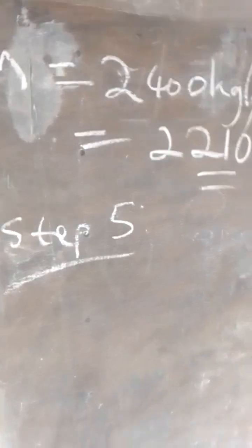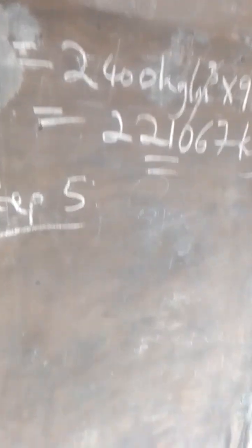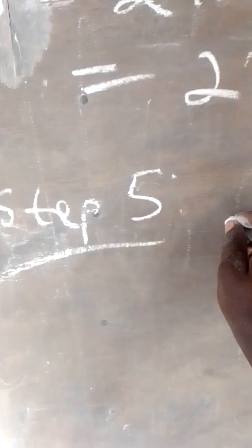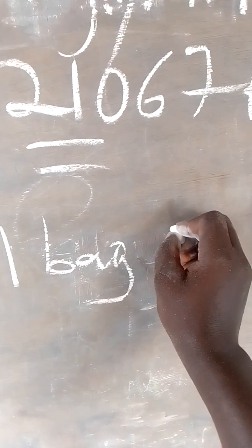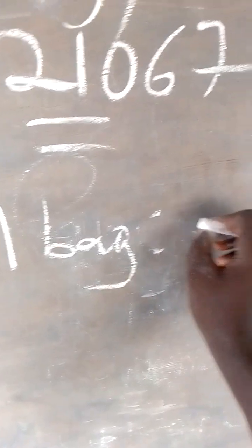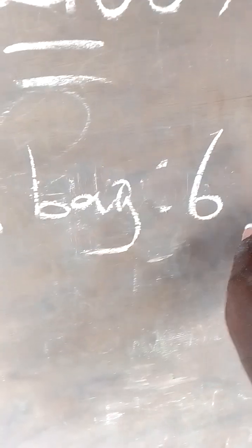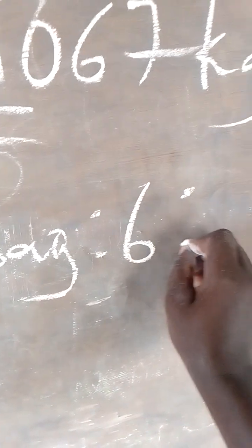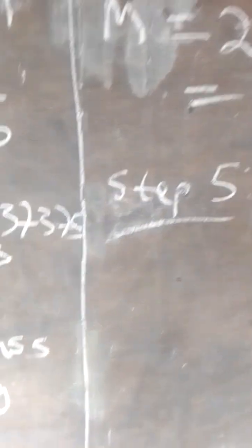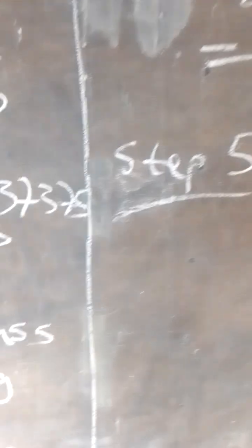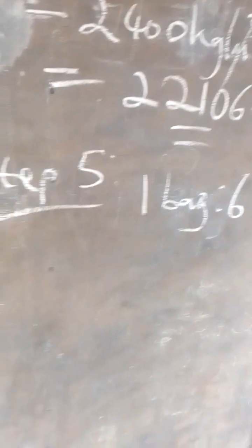For me, in my site, in my concrete work, I always use 1 bag of cement to 6 headpans of sand to 9 headpans of chippings. But in terminology, in calculating in our civil engineering terms, our young engineers will understand what I'm saying now.